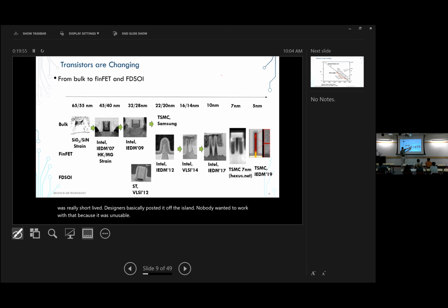What happened instead was the introduction of FinFETs, and slightly after that, moving to SOI, and the topologies that were able to control the leakages of the device. Now, FinFETs have been changing as well, and they're very different now than they used to be 10 years ago.